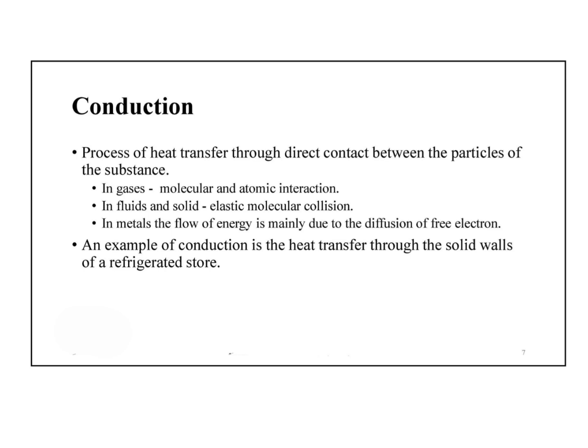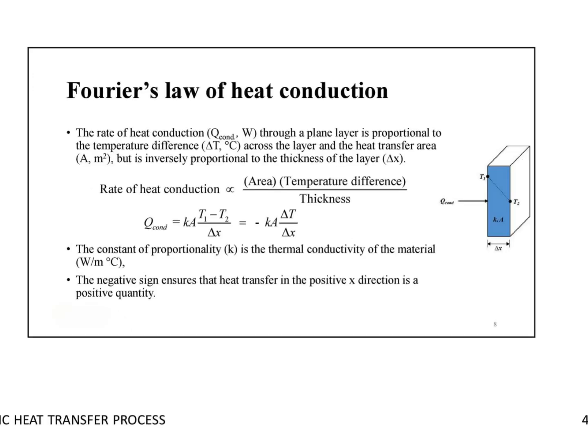Moving to next slide. Conduction. Conduction is the transfer of heat through direct contact between particles. In gases, it occurs through molecular and atomic interaction. In fluids and solids, it's through elastic molecular collisions. In metals, it's mainly due to the diffusion of free electrons. An example is heat transfer through the solid wall of a refrigerated store.